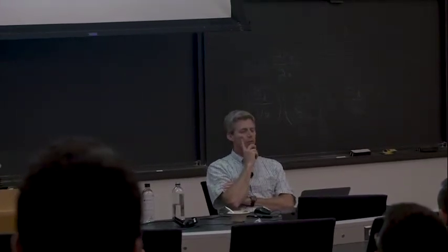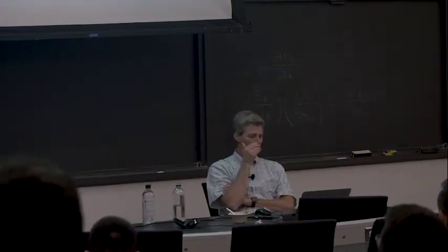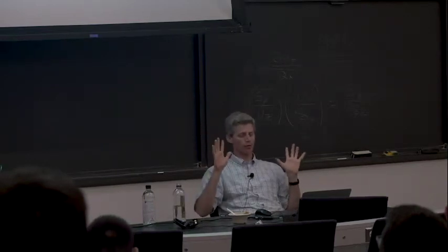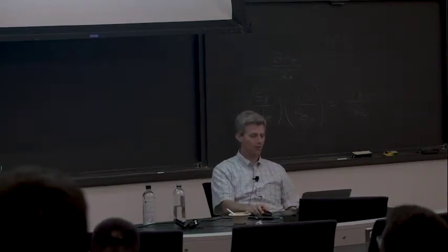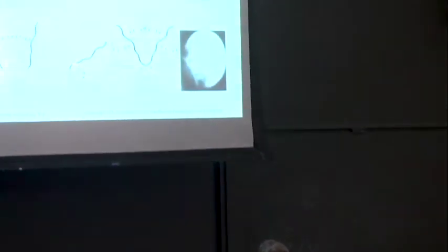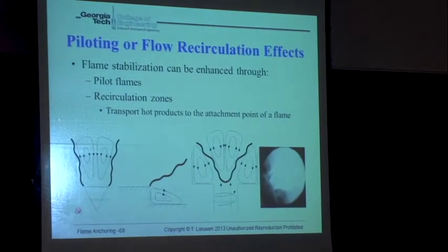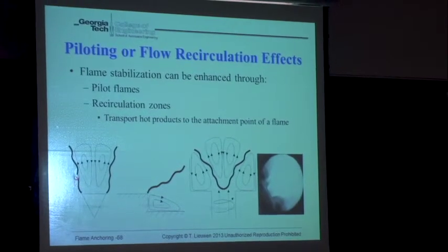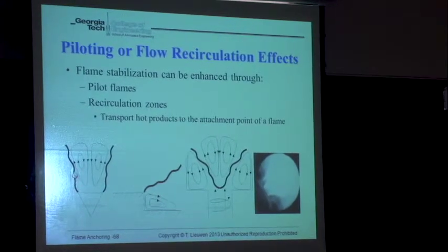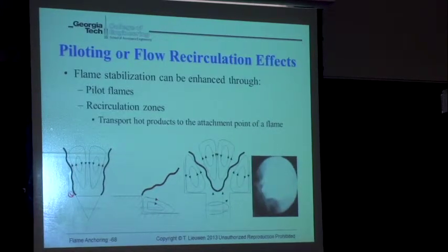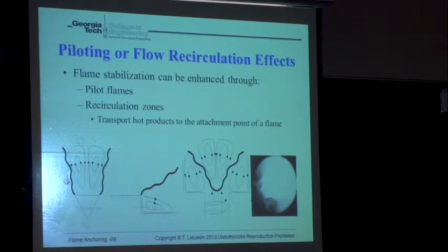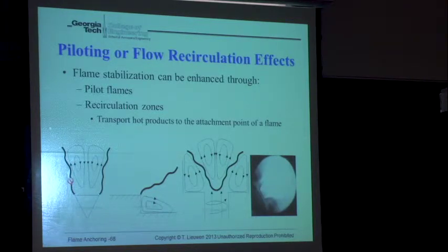It turns out that when flames blow off, a mental model for blow off could be the following. I have a flame, approach flow. I've just learned how to calculate the flame stretch rate here, even though you've told me it's complicated and I'm adding a number of opposite and negative sign. But let's just assume that I go ahead and figure that out. Hypothesis: when the stretch rate that the flame sees is bigger than the extinction stretch rate, poof, flame's gone, and that's blow off.